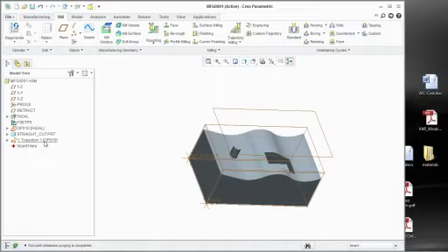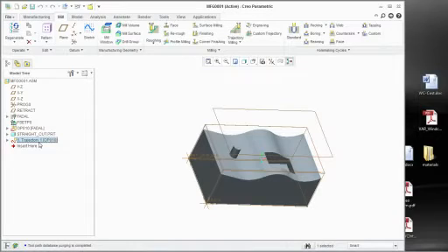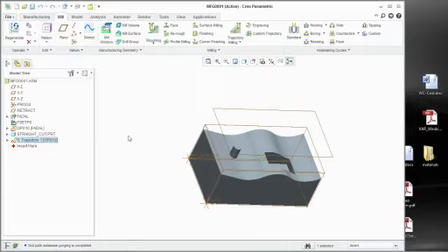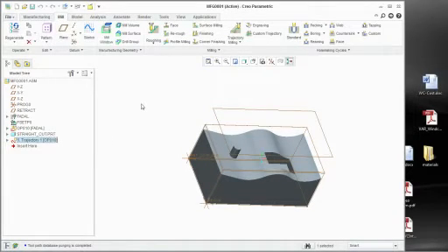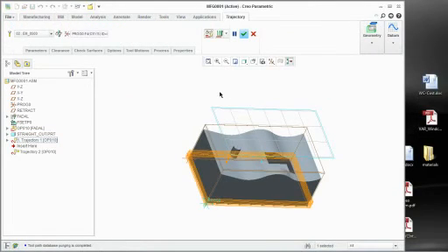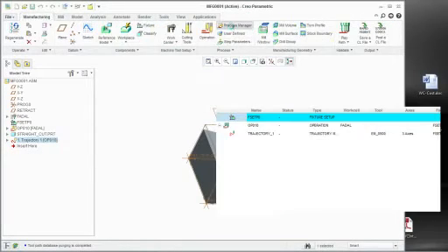So what can you do? Can you actually copy and paste this toolpath right here? Yes, you can. But what you have found is in previous versions, or if you've never done this before, is that copy does it within the machining software. You don't see copy, and you can do Control-C and Control-V, but you kind of run into this interface that you have. Now, what this allows me to do is Control-C and Control-V work well for trajectory, which you see right here, but you also have the ability to do it out of something called the Process Manager.